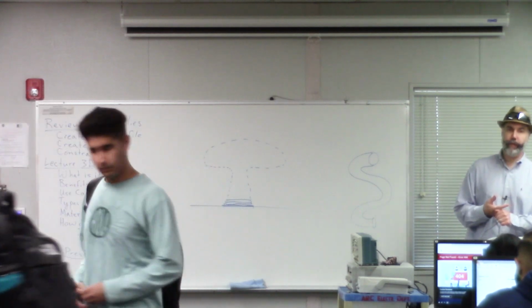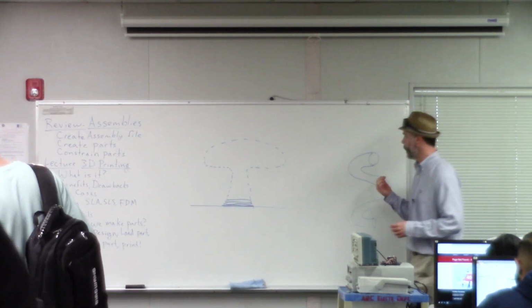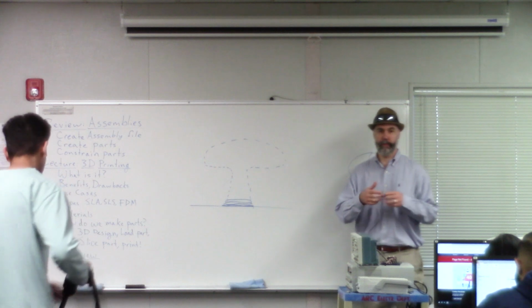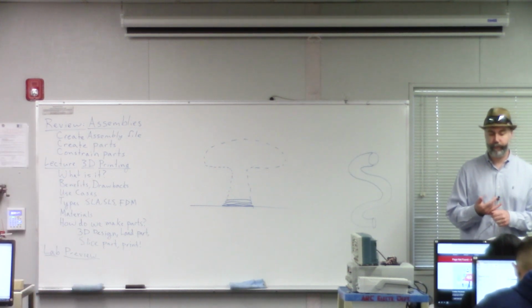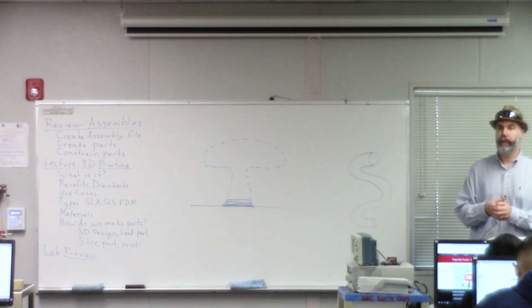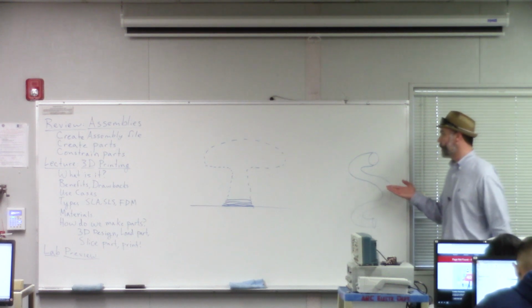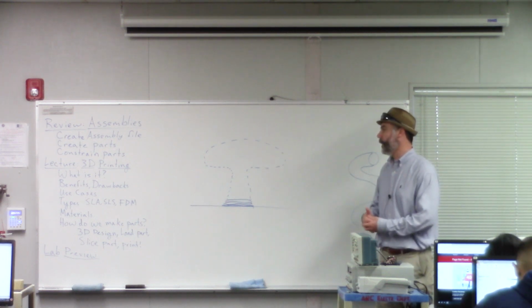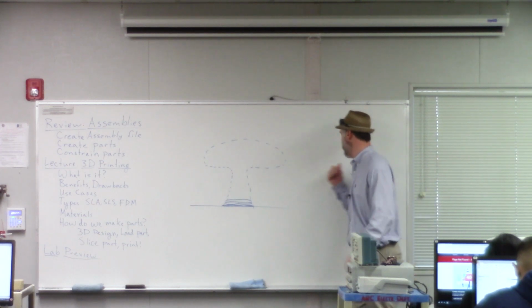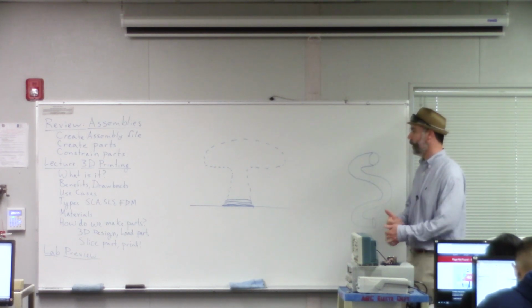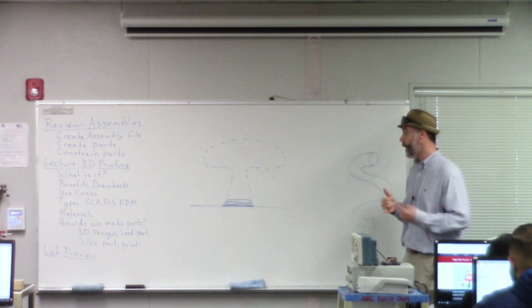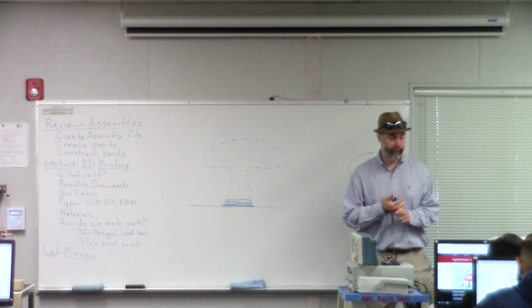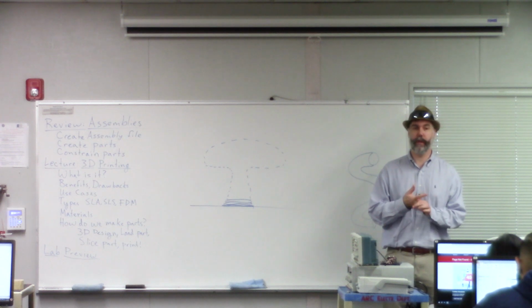It's also relatively expensive for each part if you're comparing it to making, say, 100 parts in a mold. So this is not great for mass production. It can do these really weird, wild shapes, and you have a quick cycle time for one part, but it's not great for mass production because it's relatively slow and expensive.